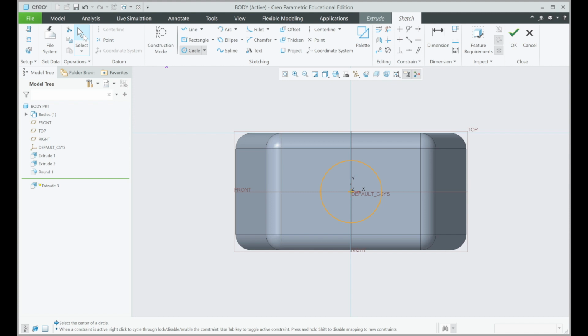Now remember, it's the select button. When we press that, if everything's good and the sketch is good to go and we're happy with it, it will go pinky purple like it has there, and we've got one dimension. The center of that circle is at the origin, so we just need the one dimension, which we're going to change to 40. When we're happy with that, we can see it's in the center, we can see the dimension there. We'll press the green tick and press OK.